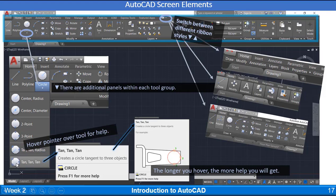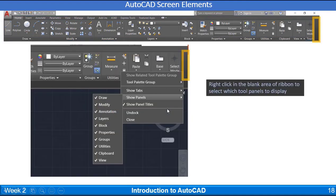So tangent, tangent, tangent. This will draw a circle that is tangent to 3 lines. And so it'll show you, if you click number 1, this is the first place you click, number 2, this is the second place you click, and then 3. It will create a circle that is touching those 3 lines, tangent, tangent, tangent. So yeah, explore all these drawing tools by just hovering your cursor over it, and then patience, wait for it to pop up with the instructions on how to use it.